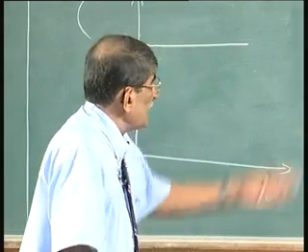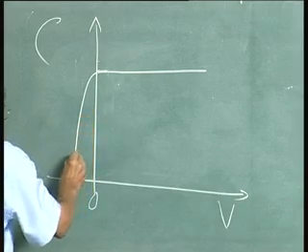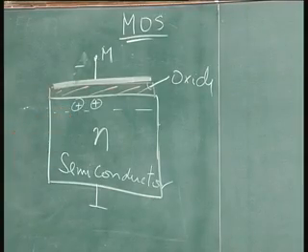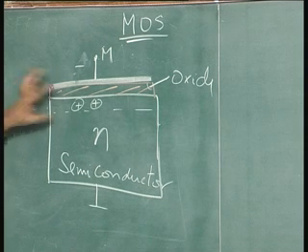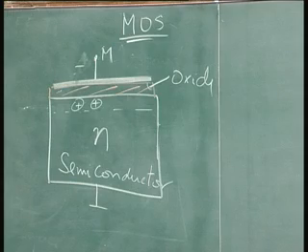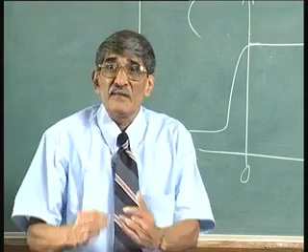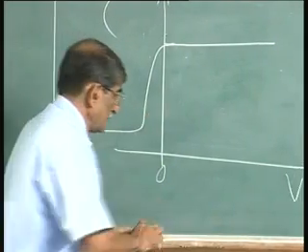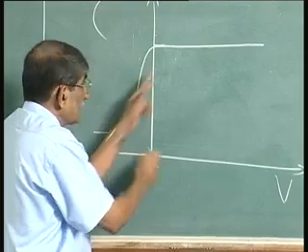So, depending upon the negative voltage that you apply, you get this till some maximum depletion layer is reached. Let me not get down into that. Right now, what I say is it will reach a maximum value, then the capacitance reaches a minimum at high frequency. Now, when you make a gallium arsenide MOSFET like this and measure the capacitance, there will be two things happening. One is the capacitance, this is of course the ideal one, at 0 it starts dropping.